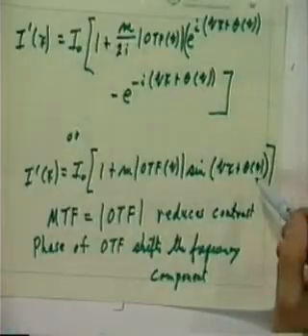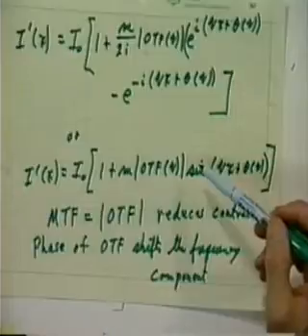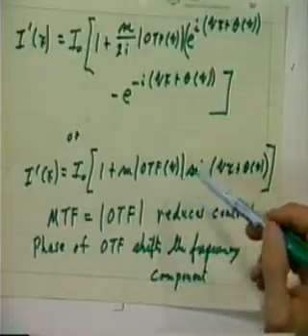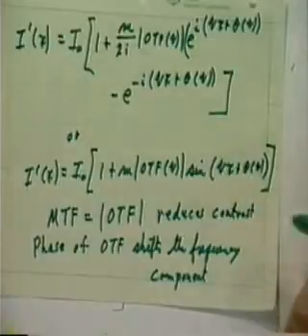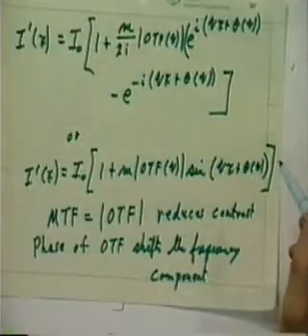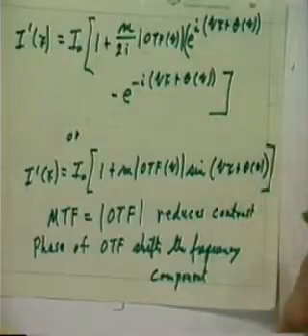And if this phase turns out to be 180 degrees, we're shifting that frequency component by half the period of whatever that frequency component has for the period. And so the shift is simply equal to theta divided by 2 pi times the period.